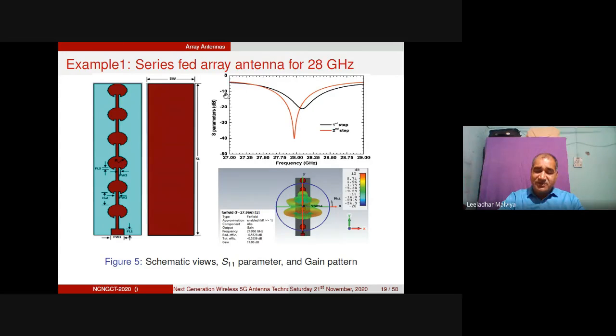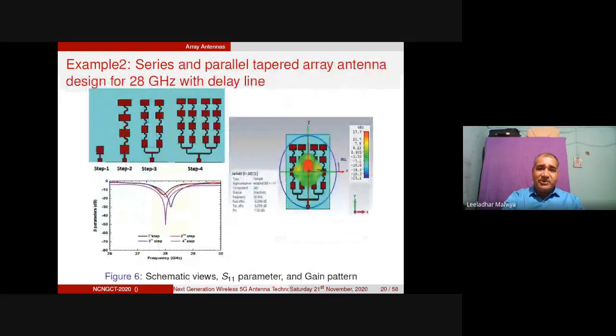These are the antennas we have designed with the help of 2:1 VSWR, meaning 89% of the power is radiated, 11% of the power is lost, right? And with 2:1 VSWR, we can find out the minus 10 dB return loss bandwidth, right? So we have done this design, communicated in one book chapter, was published elsewhere.